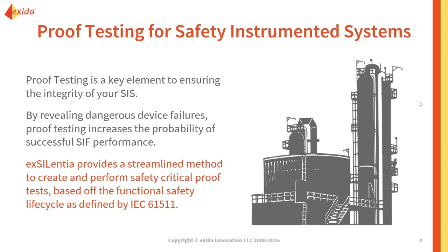As we work through the life cycle, as defined by IEC 61511, we start to create our proof test strategy through SIF identification, documenting of requirements, and then ultimately creating our SIF design, which includes some of the maintenance activities we're going to carry out on site. Once we define the intervals at which we're going to do these tests, the procedure that we're doing the test for, and once we've implemented our safety system, we also want to collect data to ensure that we're meeting our assumed frequencies of testing, that we're doing our repairs within the time that we've specified, and ultimately meeting our safety integrity requirements.